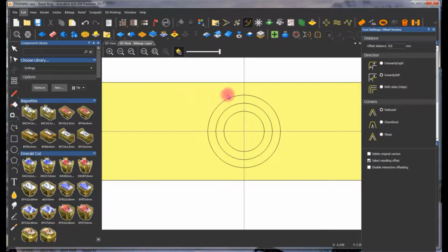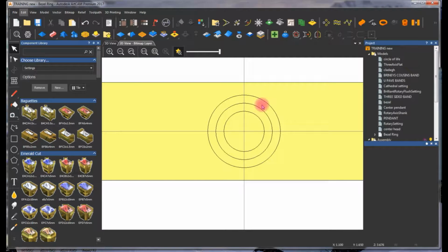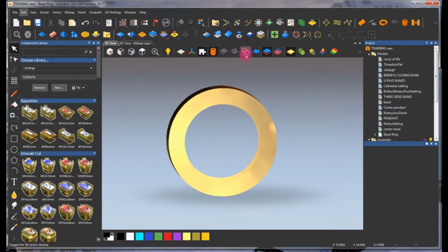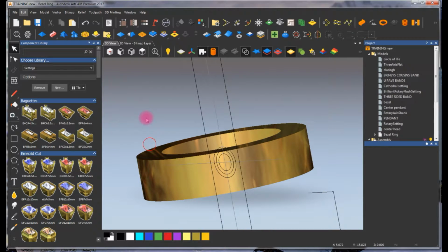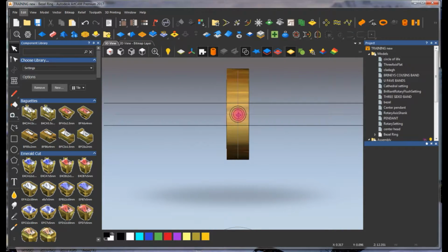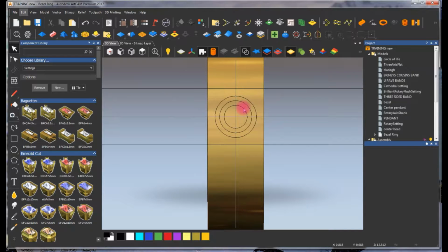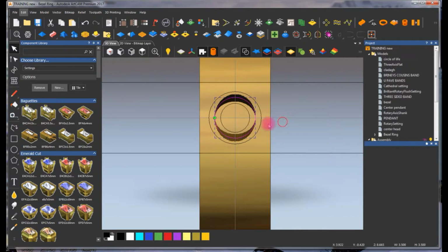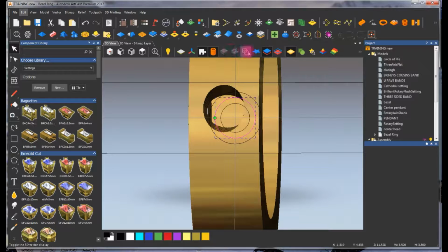First, let's see what the measurement on this is. It's 3.675, so it's pretty high. Anything above 3 millimeter, you're going to create an oval if you punch a hole in it. I'm going to show you so you can see it in real time. Let's look at it from the top. If I take this hole, or let's take the bigger one so you get a better view, and I zero this, what you end up with is an oval.